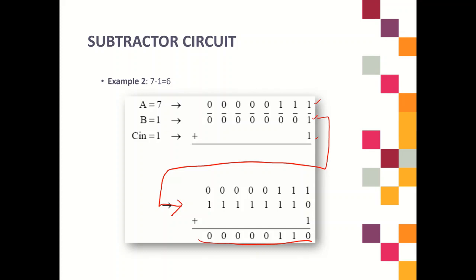It is a bit different from the previous two's complement process. In this process, you just show the whole operation in this one method. The most important part of subtraction using the subtractor circuit is the second part, which is the value of B. You need to complement each bit of B, so you will get this value.